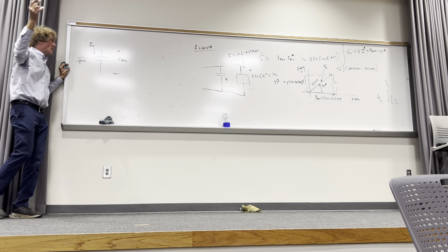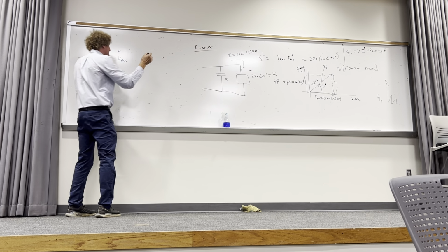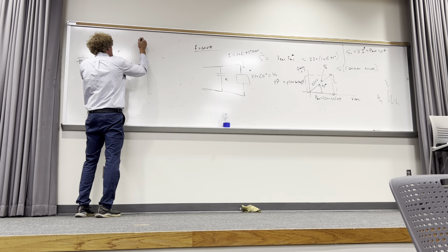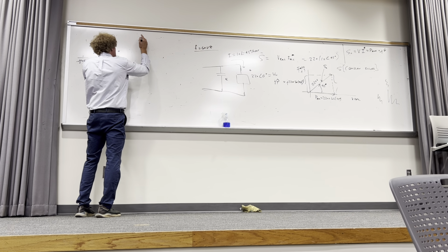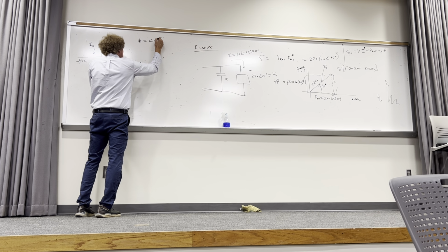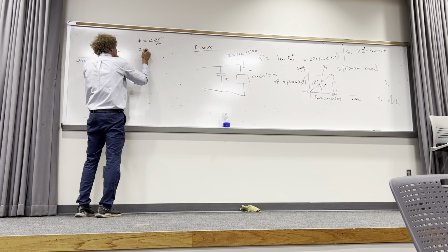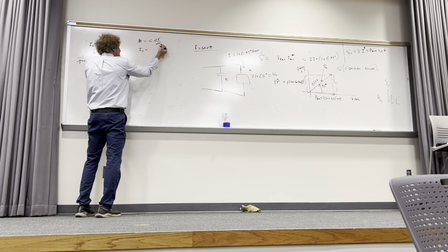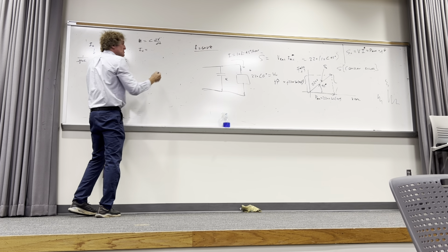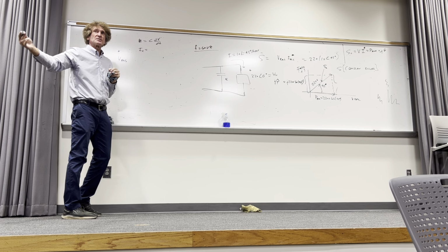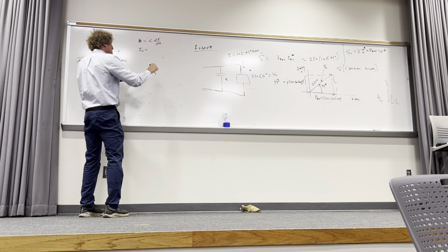All right, so now, I can do it this way too. I know that I through a capacitor is equal to C dV/dt in the time domain, or I in the phasor domain through a capacitor. Well, anytime you have a time derivative where the voltage is assumed cosinusoidal or sinusoidal, you just bring out a J omega.